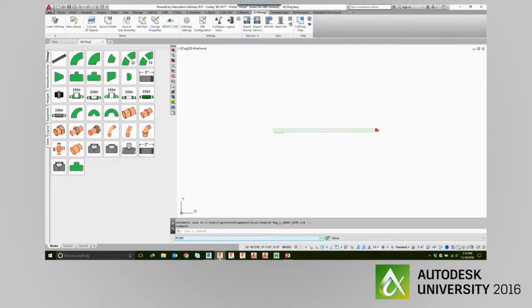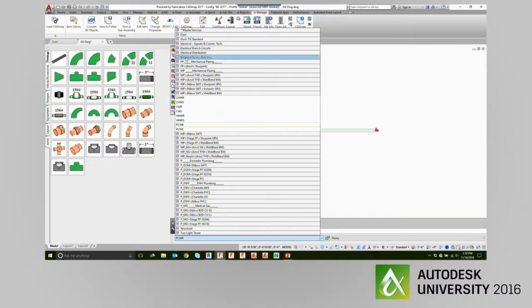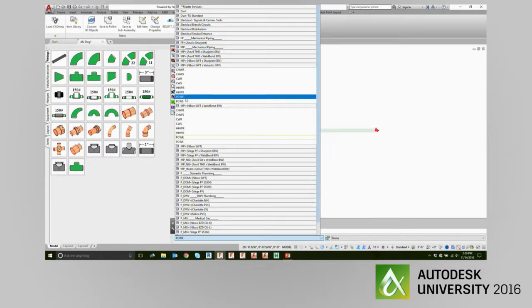So if we take a quick look back at my AutoCAD, you can see I have all these different services set up. So any service now that contains PCWR, regardless of the material type, it's going to come in with the correct color. It's reducing the number of filters that I need to have by probably, I don't even know, at least by 4 times, I would imagine. That's just with my default, let alone running jobs.